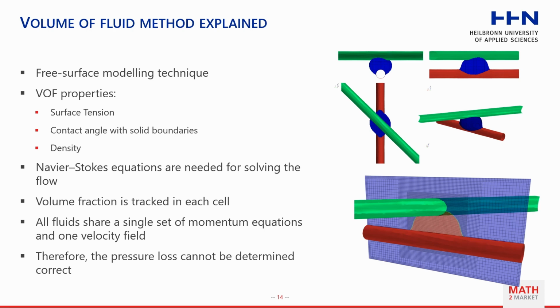The volume of fluid, the VOF method, is a free surface modeling technique. The numerical technique is used for locating the fluid-fluid interface of Eulerian phases, which can be the surface of a droplet, for example. The volume of fluid model takes the surface tension, the contact angle with solid boundaries, and the density of the fluids into account.